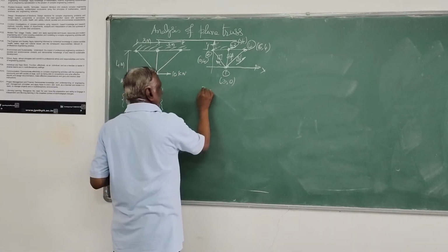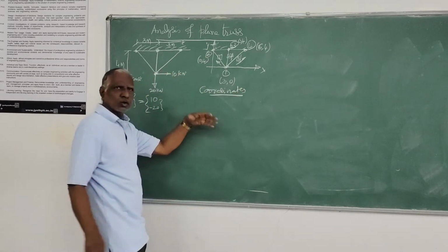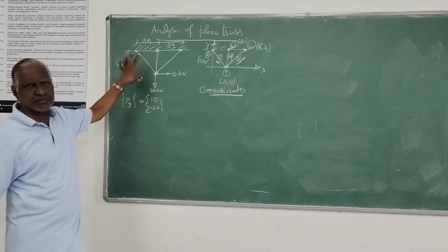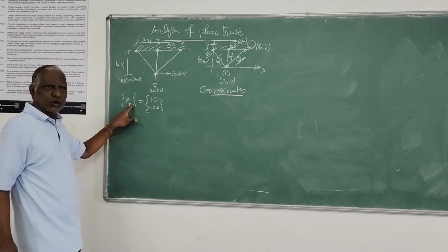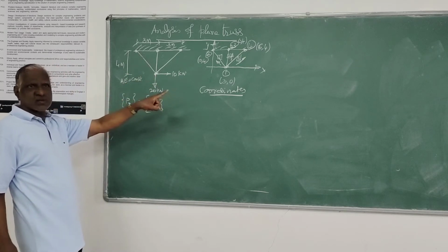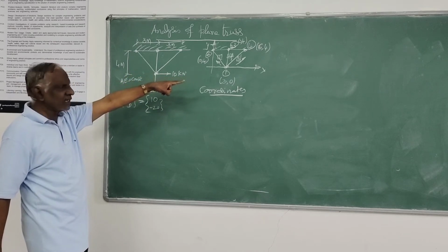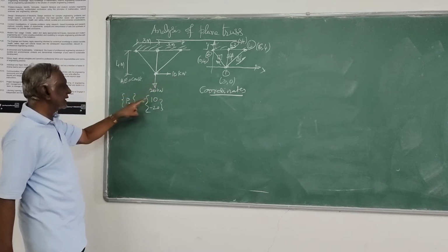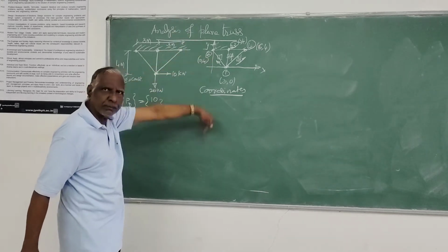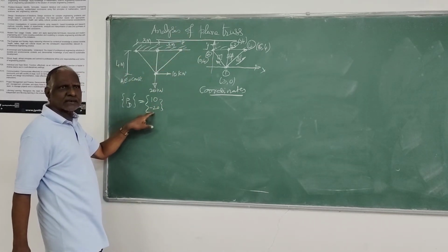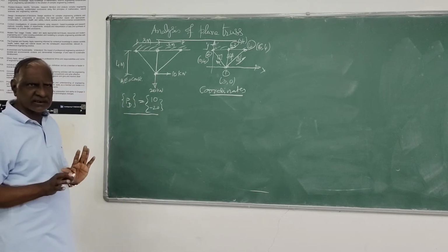These are the coordinates selected, both local as well as global, for this particular analysis. Knowing this, I will define the external load, in global coordinates only. In global coordinates, this is acting in the x direction, so plus 10. This load acts in the direction opposite to the y-axis, that's why I have attached minus 20. This is the PD external load matrix. That is the first thing.